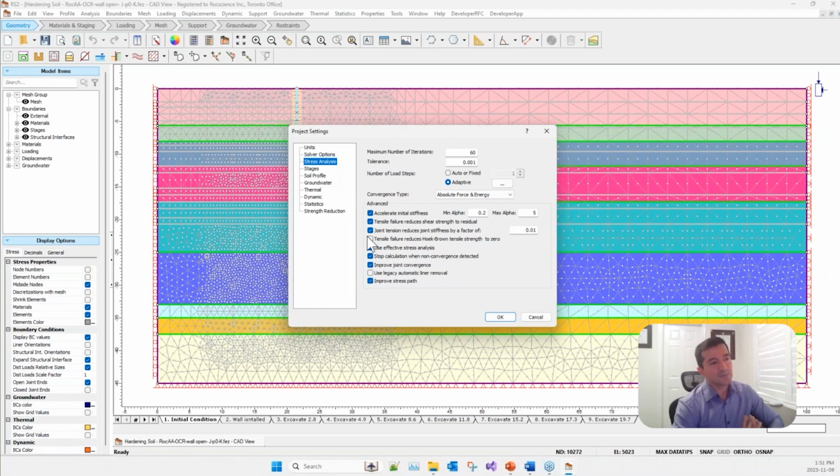In many cases that I'm dealing with a model that has convergence issues, it could be from the complexity that we have in the formulation, coupled u-p formulation, undrained material and all that. So the whole system is complex in terms of convergence, finding the solution. It could be that I'm using advanced constitutive models, which again adds to the complexity of the system. I might have convergence issues.